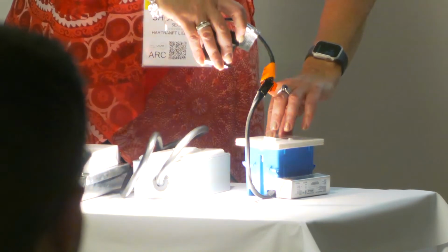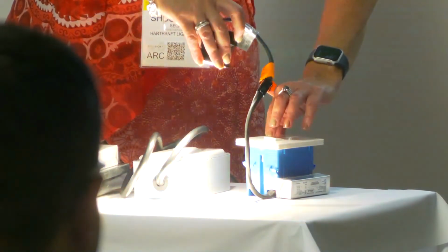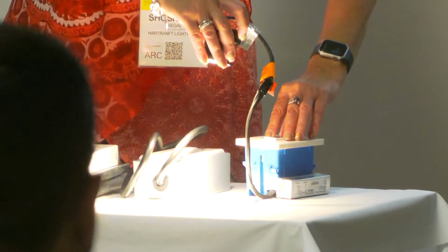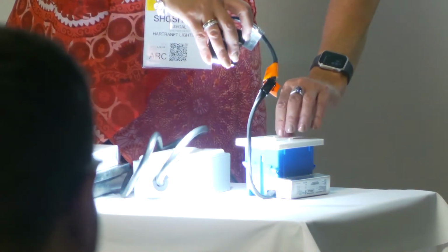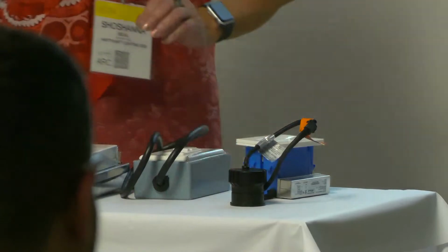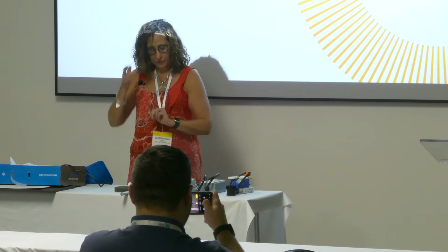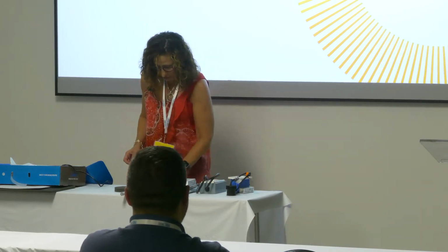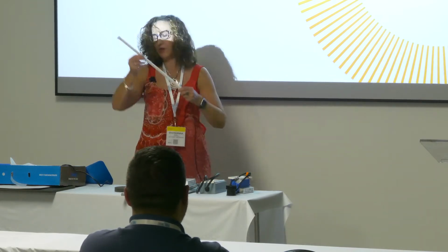color temperature, right? So this is dynamic white or tunable white. It's different from warm dim, which we're going to look at in a minute. And the thing about dynamic white or tunable white is that it requires two zones of control. Okay? Two zones of control. It requires one zone or one channel for the intensity, the brightness, how much light is coming out of the module, and the other zone is for the color temperature.